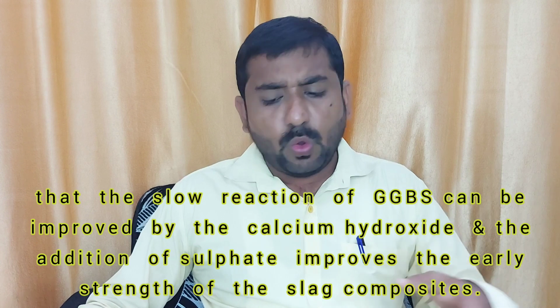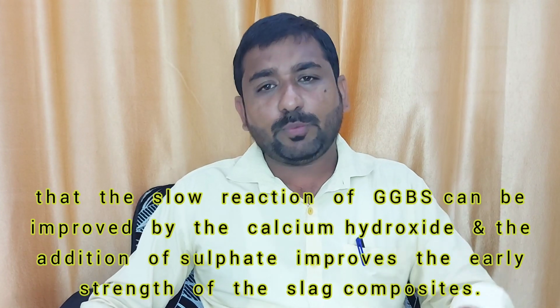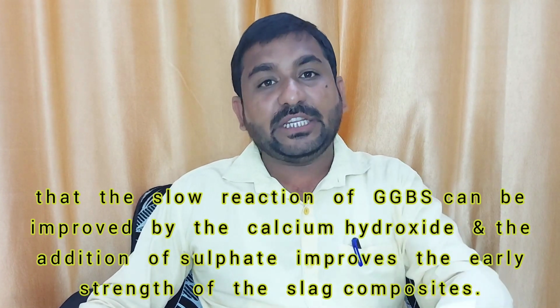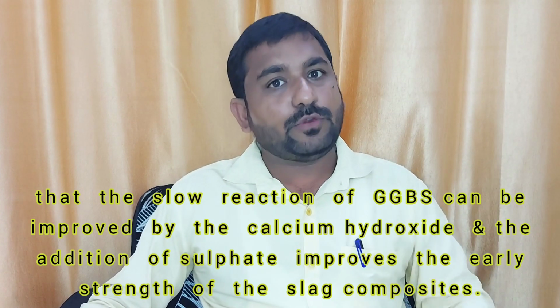To overcome this issue, we have to provide calcium hydroxide and additional sulfates, which we generally provide through hydraulic cement, OPC 53 grade. But we also have to counter the strength development, not only the setting time, the strength development also.